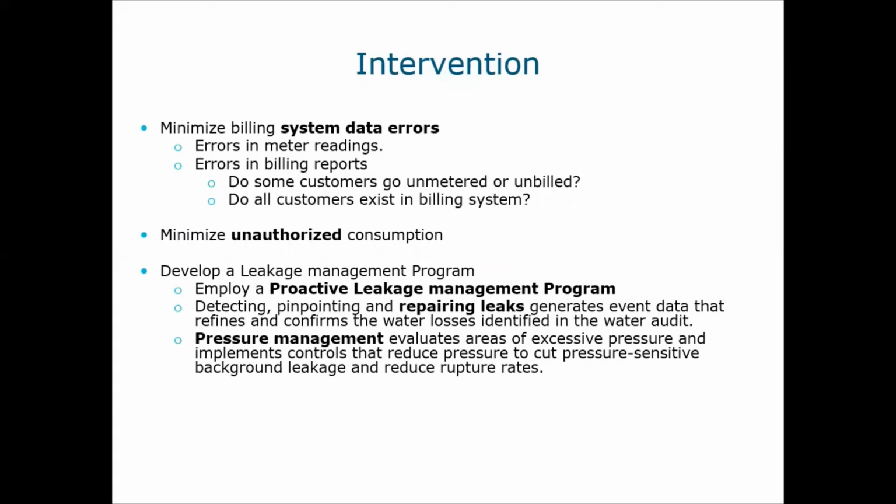And then we have developed a leakage management program. We want to try to employ a proactive leak management program. Detecting, pinpointing, and repairing leaks generates event data that refines and confirms the water losses identified in the water audit. Pressure management evaluates areas with excessive pressure and implements controls that reduce pressure to cut pressure-sensitive background leakage and reduce rupture rates.